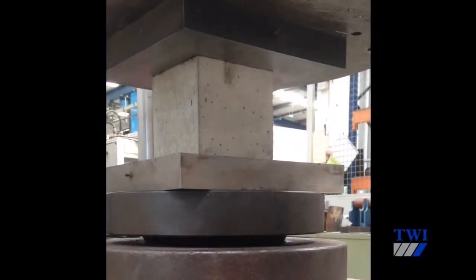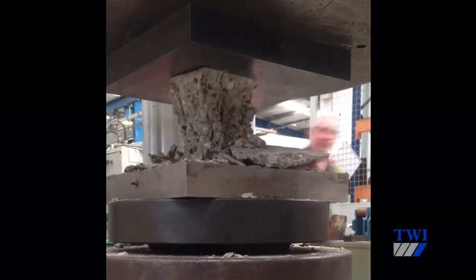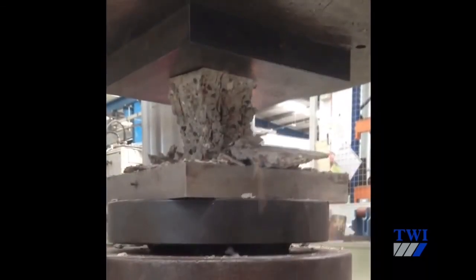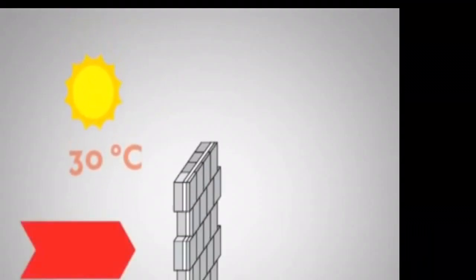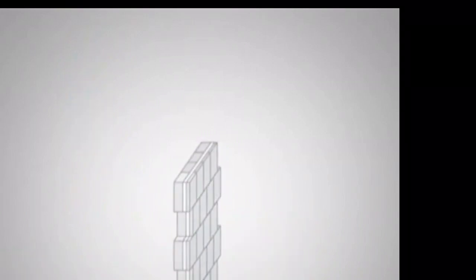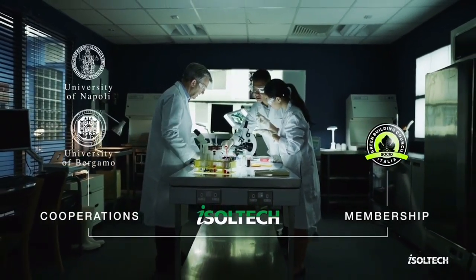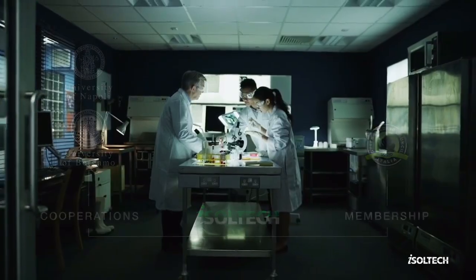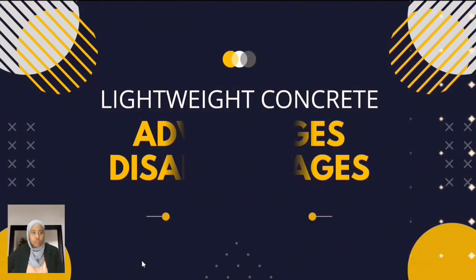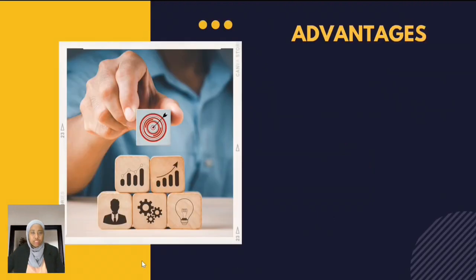Durability: aerated concrete is only slightly alkaline due to its porosity and low alkalinity. It does not give rust protection to steel, which is provided by dense concrete. Thermal insulation: the insulation value of lightweight concrete is about 3 to 6 times that of brick and about 10 times that of normal concrete. Quality control: better quality control is exercised in the construction of the structure with lightweight concrete products owing to the use of factory-made units.